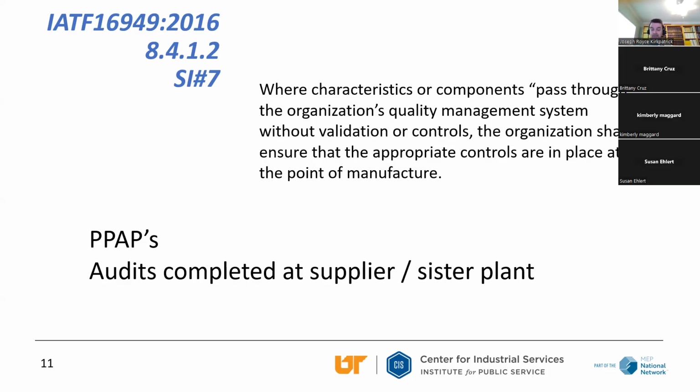How could we do that? Anybody got any experience? Yeah, you would get PPAPs from those suppliers. That's one way to at least show that they've done a PPAP. We could audit them. We could do sample inspections on them periodically, maybe an annual layout or something like that. That's one way to do it, but there's other ways.